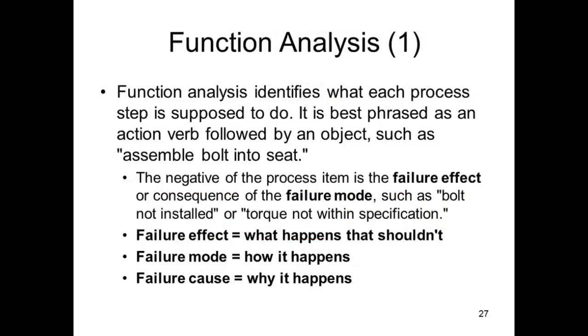Function analysis identifies what each process step is supposed to do. It builds on the structure analysis. The structure analysis shows what the process steps are. The function analysis tells us what each process step is supposed to accomplish, in this case, assemble bolt into the seat. The negative of the process item is the failure effect, such as bolt not installed or torque not within specification. The failure effect is what happens that shouldn't. In other words, the bolt is either not installed or is installed with the incorrect torque.